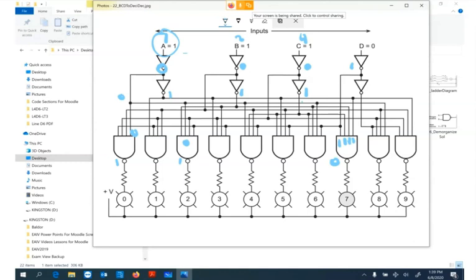This is going to come back in process control. Sinking switches a path to ground. So it's like switching the neutral or switching the negative side in this case. Where sourcing would be switching the other way. We would need to have a 1 there to turn it on. But the key point here is the voltage. In order for a 1 to turn that on, then this would have to be a ground instead of a source. So that's a little messy. If you didn't see that point, that's what I'm here for, to point out those little details, and hopefully you can wrap your head around it.